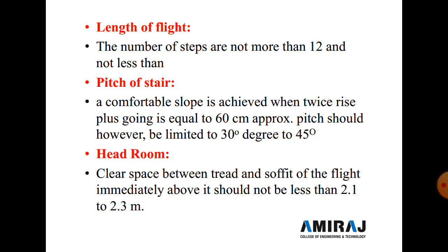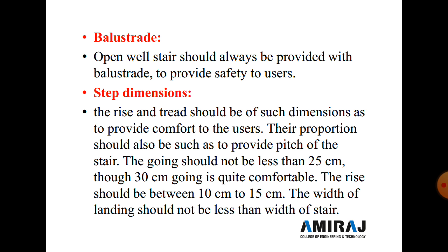Now next is headroom. The clear space between the tread and the surface of the flight immediately above it should not be less than 2.1 to 2.3 meter. It is nearly like the distance from the flooring level to the lintel level. Now balustrade. An open well stair should always be provided with a balustrade. It is to provide safety to the user.